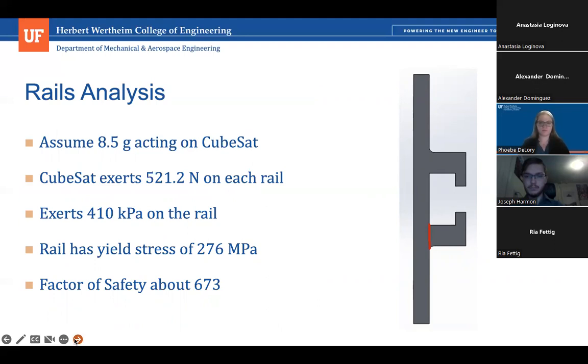There's a really small fillet on the upper corner inside the T slot. We should actually have them. I don't think this image shows them. It's a very small fillet too. Yeah, I was talking about the inside portion. Yeah, it's a very small fillet. It's one that would be manufactured with the T slot, with the slot mill. Okay, thank you.